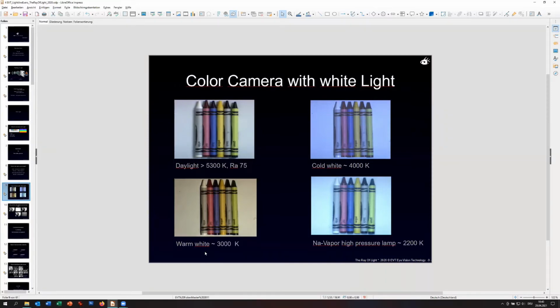You cannot do it every second. It takes some time to do the white balancing, so you have to do it maybe once every few hours to be sure that the camera sees the right color based on the current illumination.